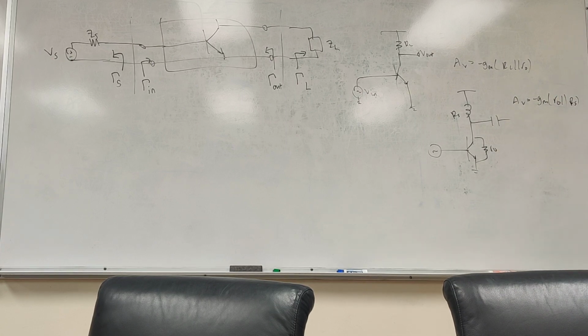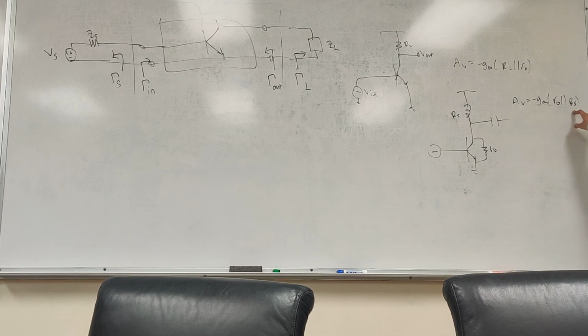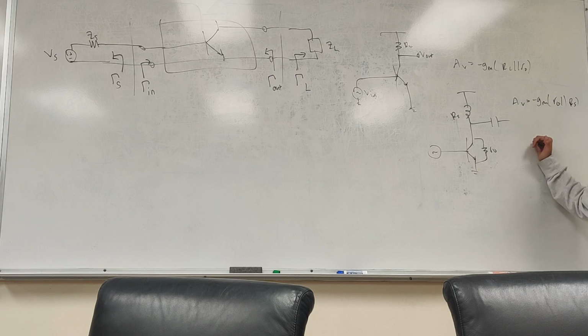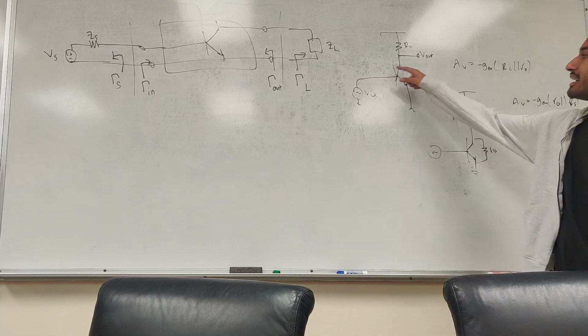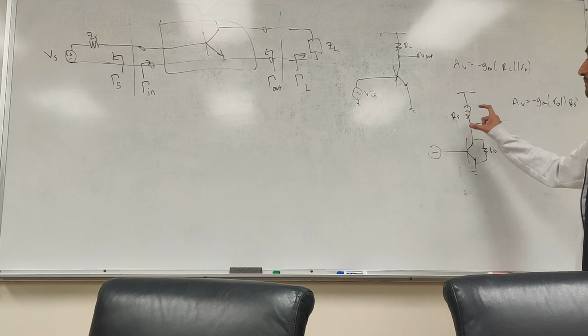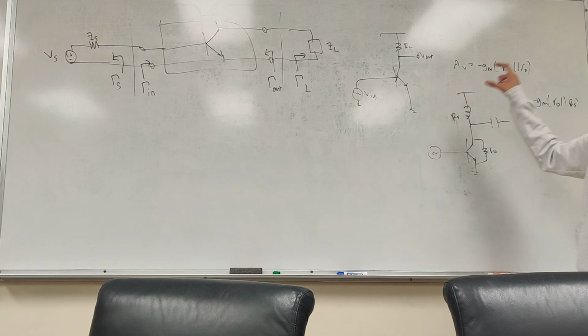So this is kind of troublesome. Sure, we get the benefits of slightly higher gain from this, but there's still this. So it's not our maximum gain available. What we want to do is say we pick a random transistor. We use the MMBTH10. Get as much gain as we can out of it, which means we really need to understand how this thing looks. If we understand what this thing looks like, we can put it into another network and squeeze as much performance as we can out of it.